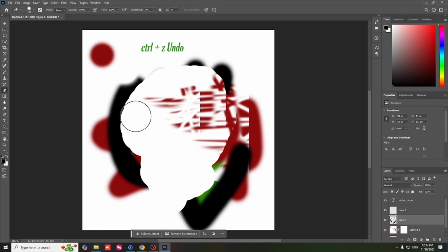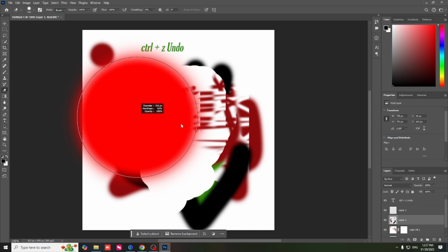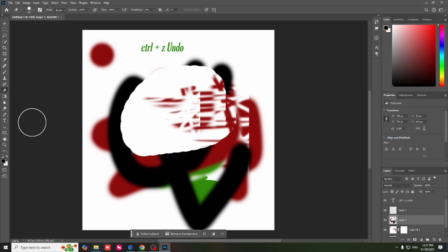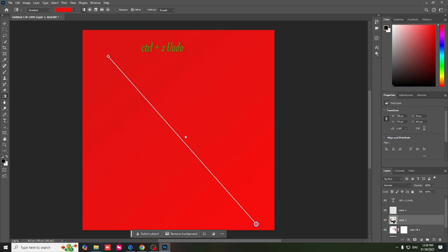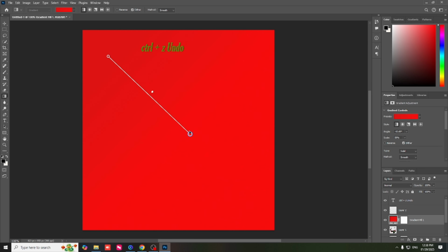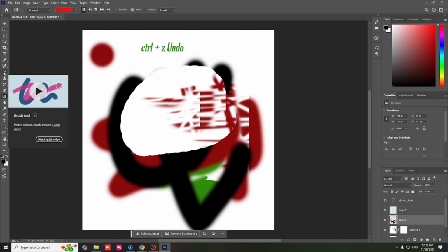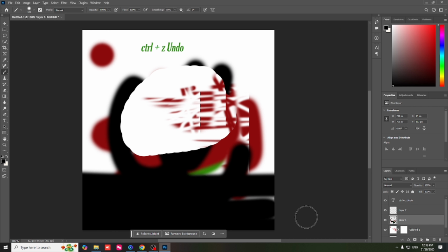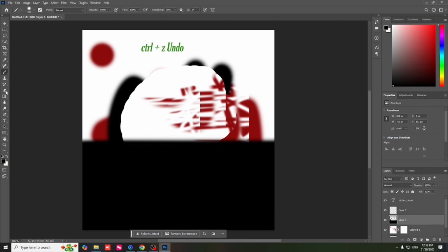The eraser is a pretty simple tool. You can just erase whatever is in the layer that you're working on, layer 1 or layer 2. It could be brushwork, painting, or a PNG. And you can change the size or hardness in the left corner of the settings. And one easy shortcut is that you press your Alt button and then your right mouse click, and when you drag like that, it changes the size directly.